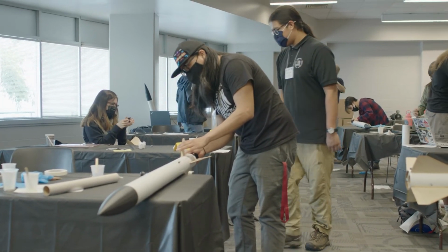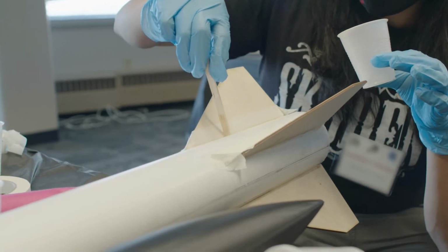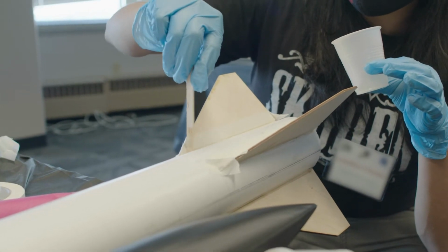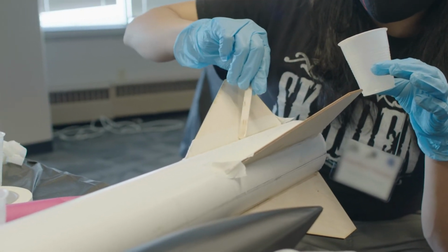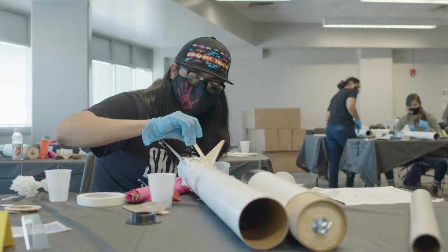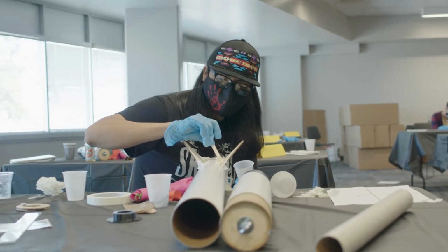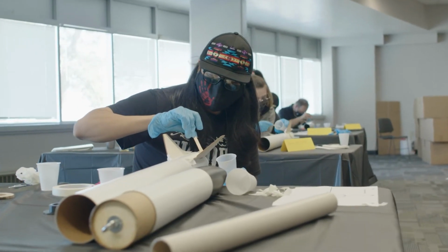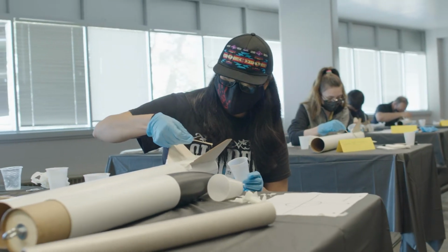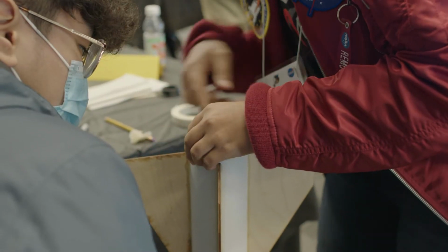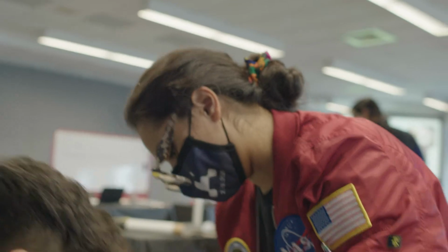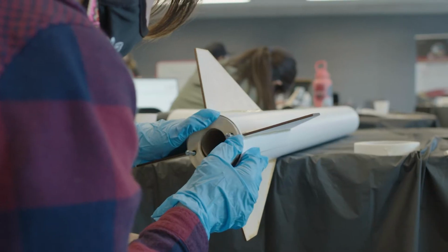Cyanoacrylate is the chemical name for superglue adhesive, which solidifies in seconds and is suited to small plastic parts. Cyanoacrylates have relatively little gap-filling capability, so they require close-fitting joints to bond effectively. Wood glue, or polyvinyl acetate, has better gap-filling properties. As the name implies, it is most effective at bonding porous materials like wood and paper.